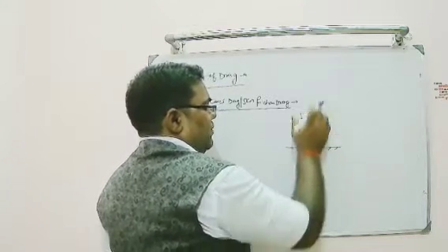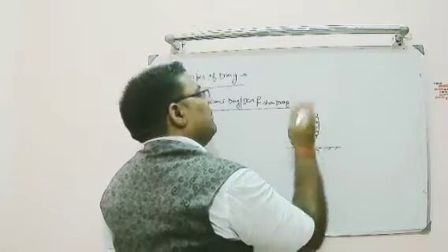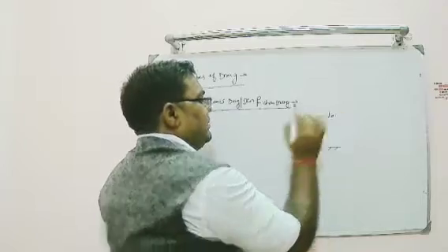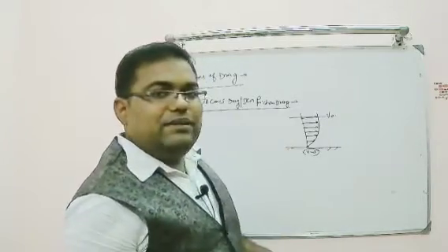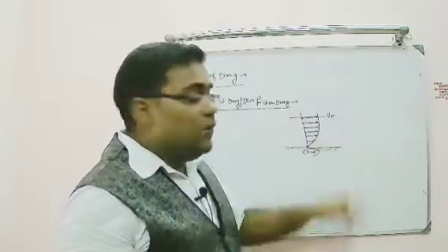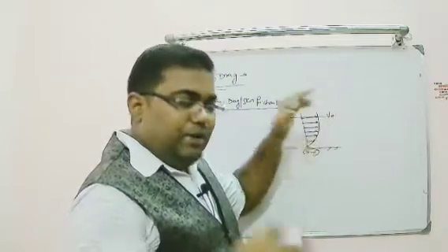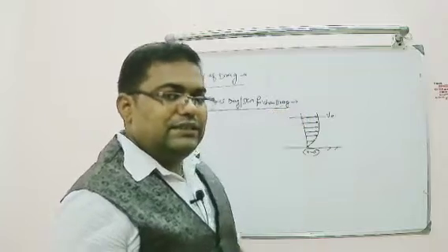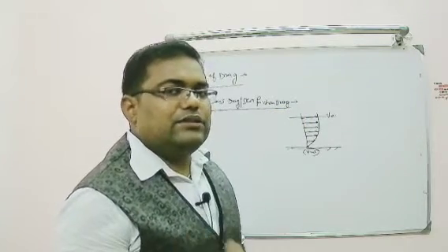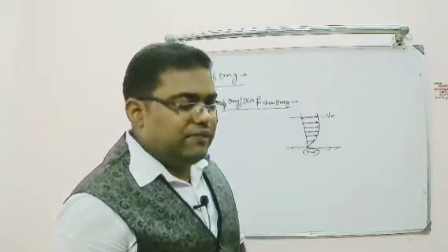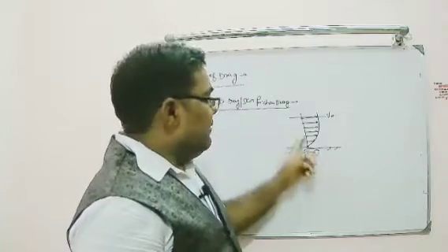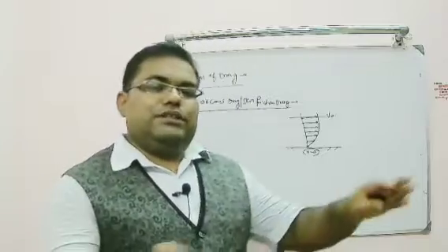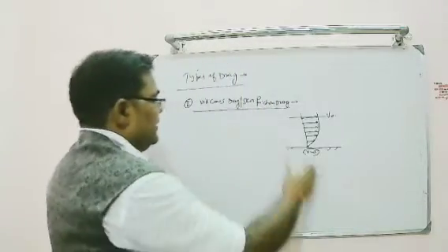If you go away from here, it will be parabolic up to a certain height. After that it becomes the free stream velocity again. So the effect of viscosity is negligible, completely zero at this height. Below this there is a change in velocity. As you move towards the solid boundary, velocity keeps decreasing. If you move away from the solid boundary, velocity increases, and after a certain time it becomes the maximum velocity, the free stream velocity. This is known as the velocity gradient.